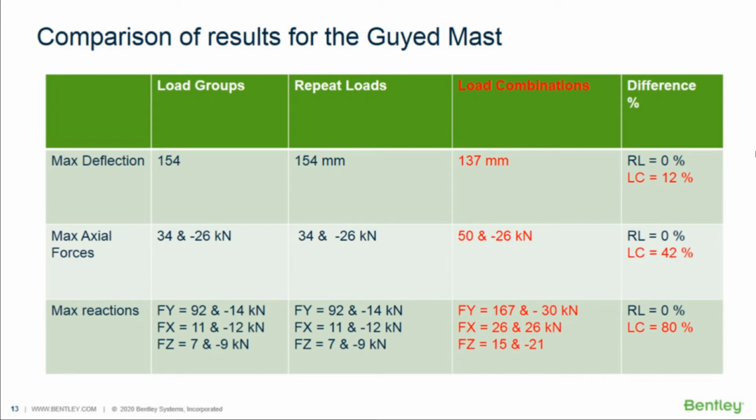Some of you may be aware that the reference loads got a new name called load groups in the physical modeler, starting from STAAD.Pro CONNECT Edition. The analytical modeler still calls it reference load, but the physical modeler in STAAD.Pro calls it load groups. So when I say load groups, it is reference loads.